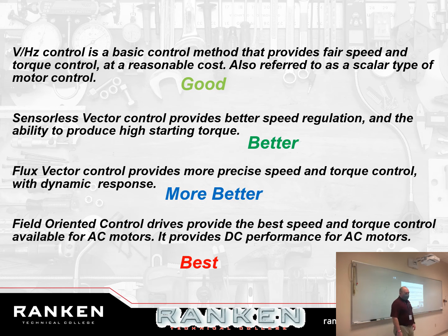So there are 4 different ways of controlling it. The majority of them are going to be run off of what we call the volts over hertz ratio, right? Most of the drives you're going to encounter are going to run off volts over hertz. Okay? You change the frequency, it changes the speed of the motor, and it changes the voltage output to the motor. All right? Hopefully it doesn't affect the torque. So this is actually most of the way. It's relatively cheap. All right?